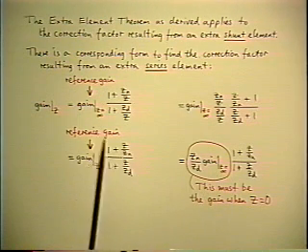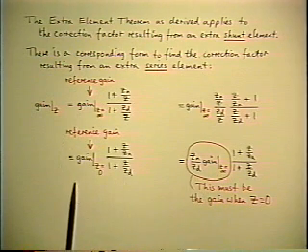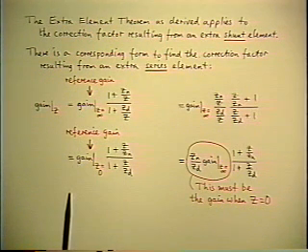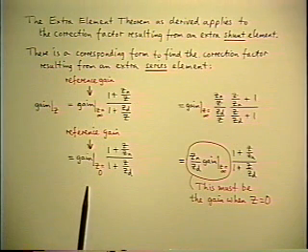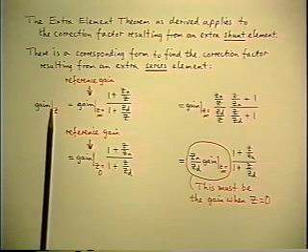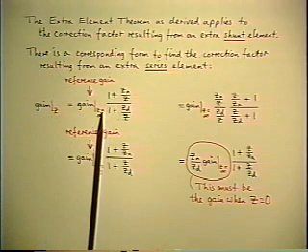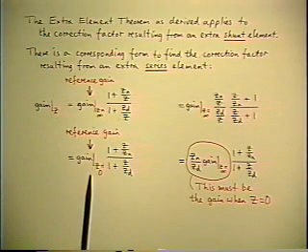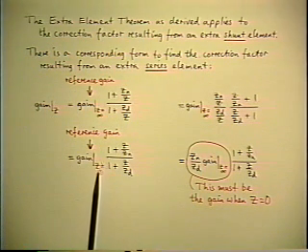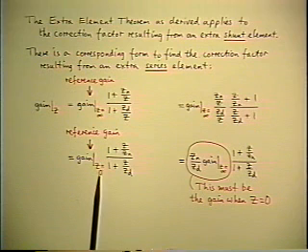So finally you can write it in this form that I've written under the other one, and that is the dual form of the theorem. It's a different choice of reference. In the original version of the theorem, you get the gain in the presence of Z in terms of the reference gain when Z is infinite. In the other form of the theorem, you get the gain in the presence of Z when the reference value of the element is 0. So you have your choice.